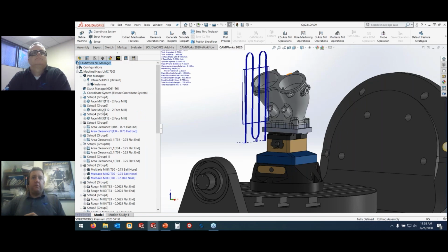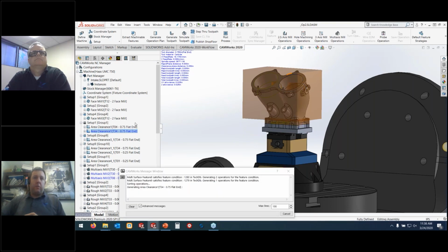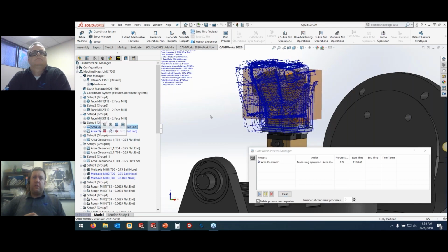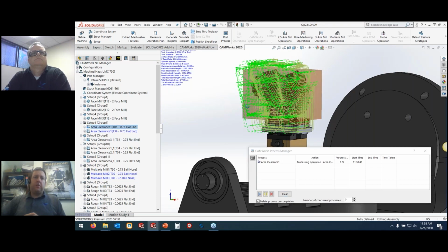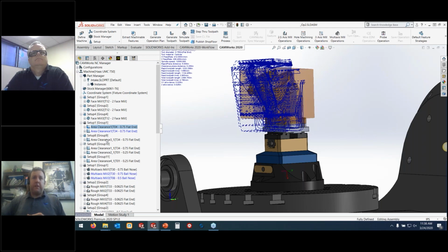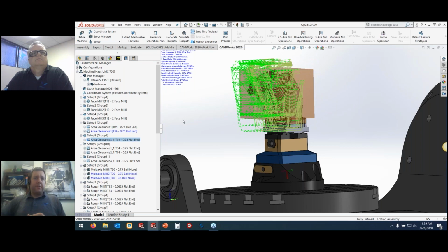So we've got our face mills. We've got our rougher for our ports here. Let's get that rougher for our other port generating there, whilst we're talking about some of this other stuff. And then we've got our roughers as well. So these are the ones that we imported down here, set from the long version of this file. So we've got our roughing right here. We've got our other roughing right here. We might want to go and update the rest machining.